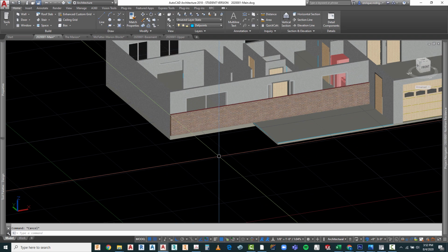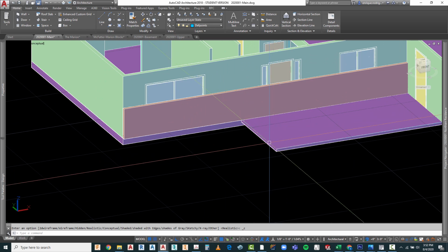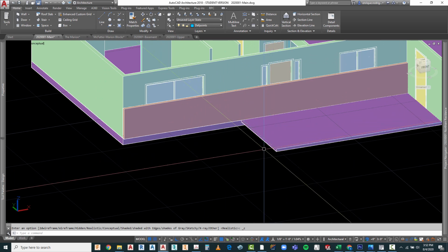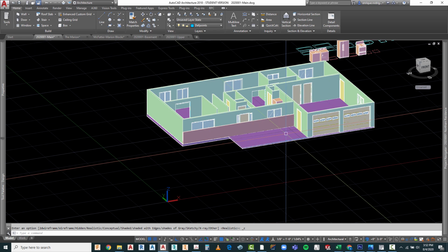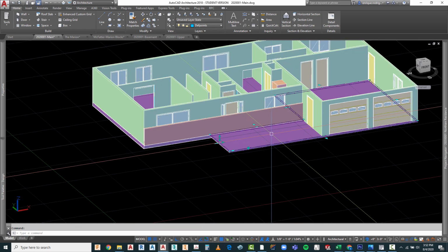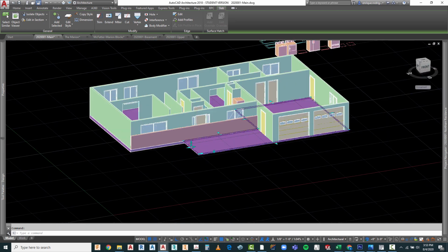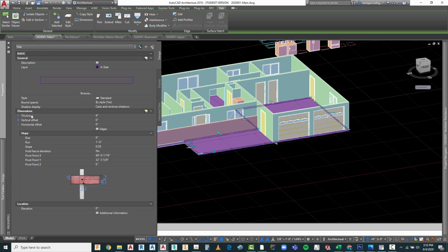That is our floor structure for the main level. I'm going to change this to conceptual so we can see the difference. Now this one I can leave at 4 inches, even though it's going to have what we call a thickened edge around here and also around there. But the top of this slab is right now indicated on where our grid is. In other words, it's at 0, 0. And even though it's 4 inches deep, it's not at the right location. We need to drop that down. So with it highlighted, let's go to the properties.